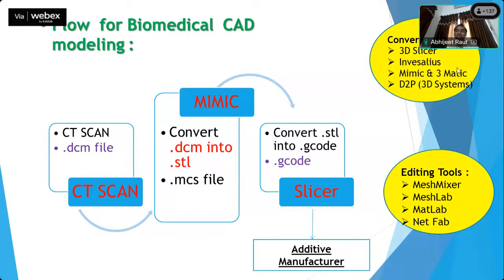Pre-processing is essential. If we are starting from engineering CAD, all optimization can be done in the engineering CAD software itself. But for biomedical applications, if we are importing the data from a CT scan or MRI, or we are planning something in those particular software, further STL processing is important, right? For that, there are various tools, for removing the noise or cutting those parts, whatever is needed.